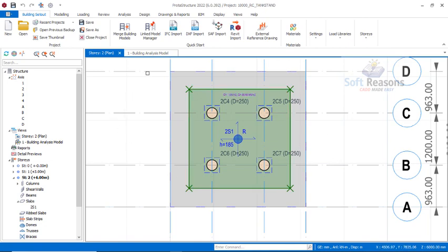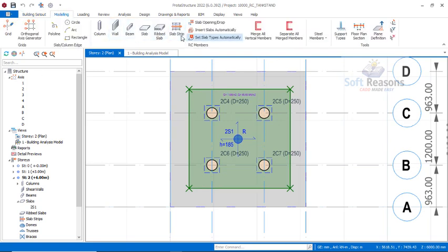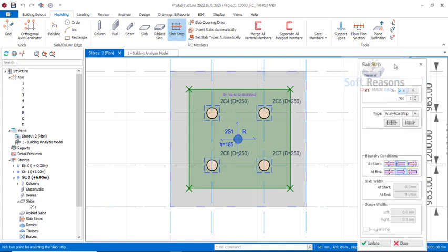It's all right. So the next thing we do is to generate strips for the slab. You go to the modeling tab and click on the slab strips right there. In the slab strips dialog, we are not using the analytical strips because we used finite element analysis, so we use the FE strips selected just like this. Then we click the second one, which is the fixed bound strips, and the analysis result source is going to be FE analysis, floor analysis. After having done that, we now start to place the strips. We pick this point and then take it over to this point and click.